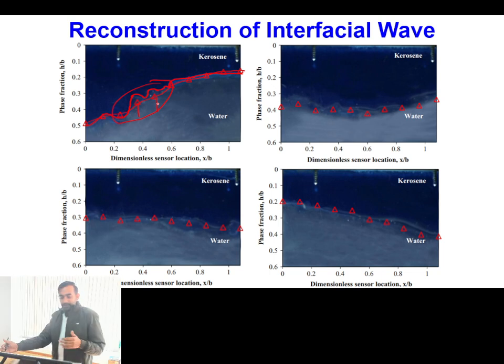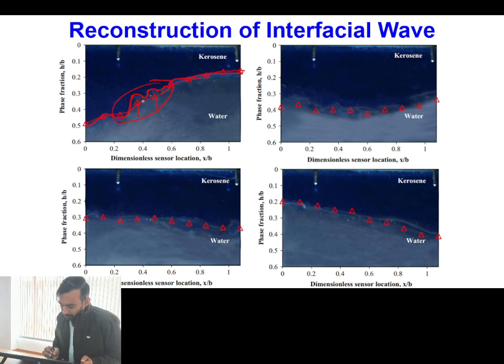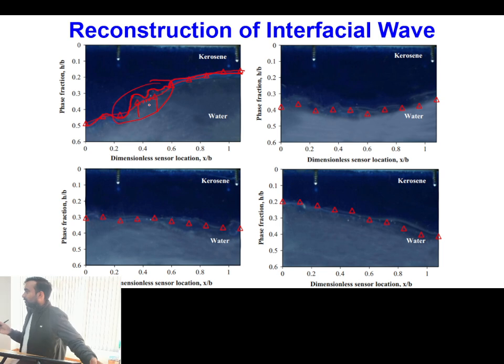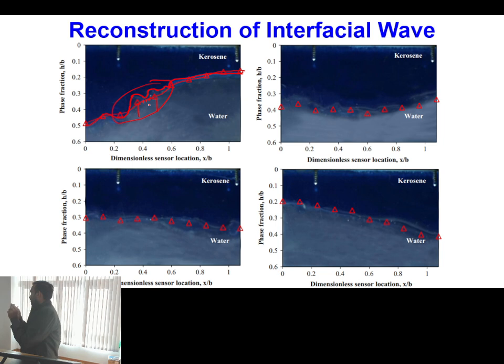Okay, so in order to improve accuracy in this system, what we need to do? We need to have more data points. If we have to go for more data points, then whatever the size of the photodiode we have taken, we have to consider thinner photodiodes, because then only we will be able to closely place them. Is this one clear?